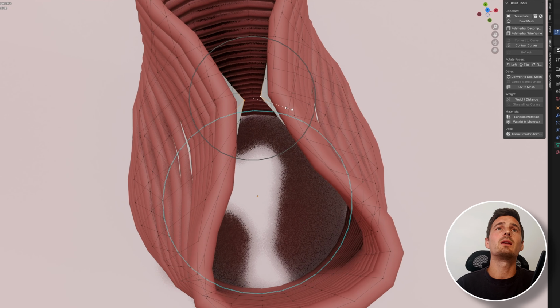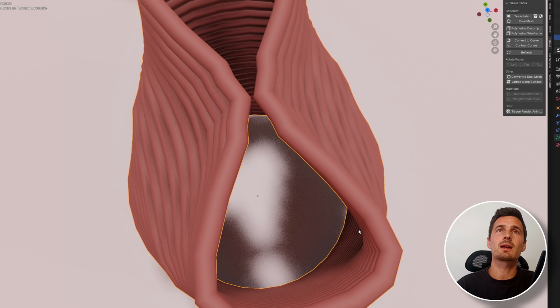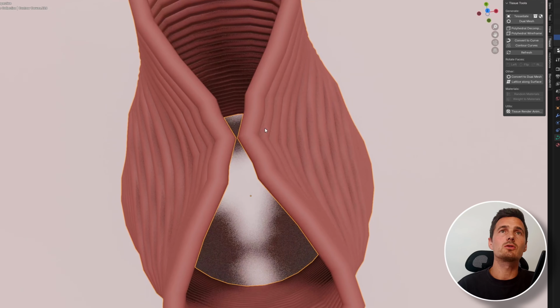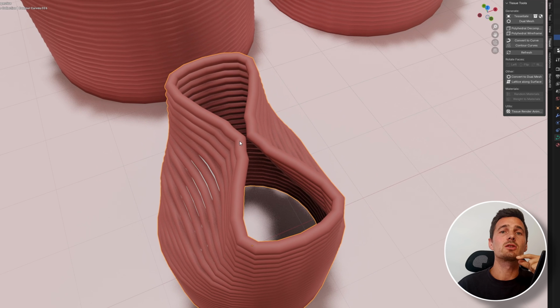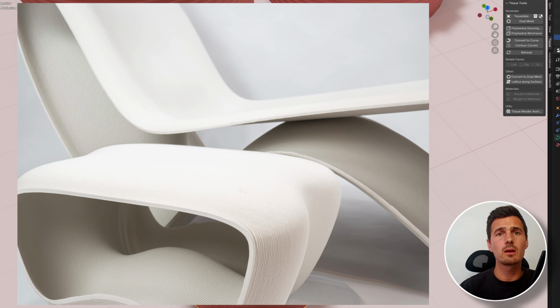You need to design with the layer width in mind. If the layers are going to be exactly in the middle of your surface, the space between those two surfaces has to be exactly one layer width. Then they will perfectly meet each other and barely touch, and this will create extra strength for certain objects. For example, in the lounger chair that we have at More Than Layers, you can see that it barely touches, and this creates extra strength within the object.